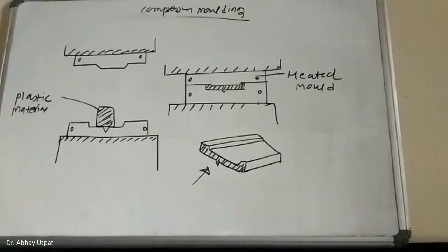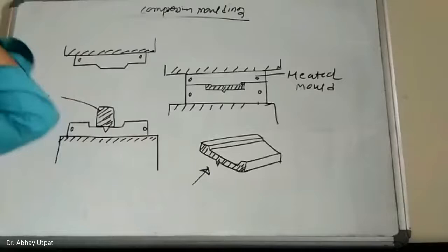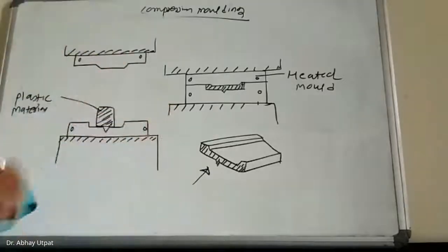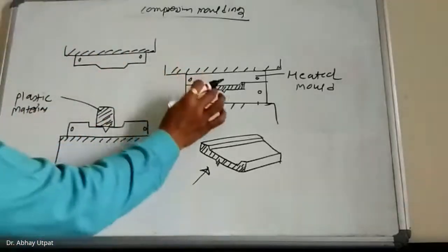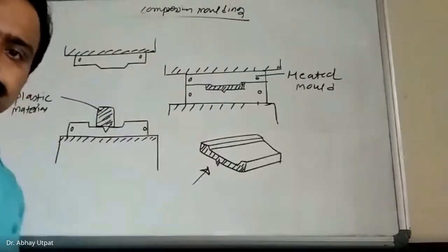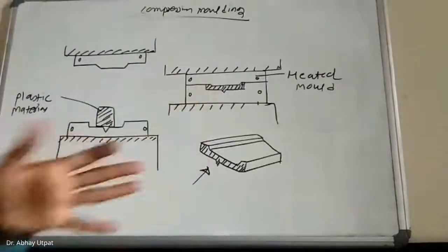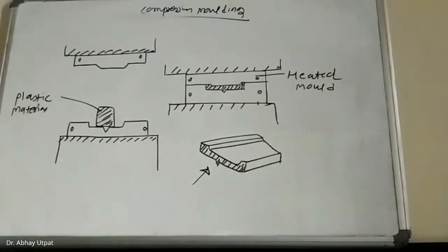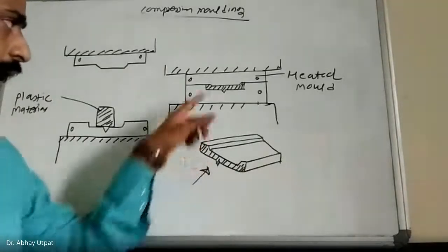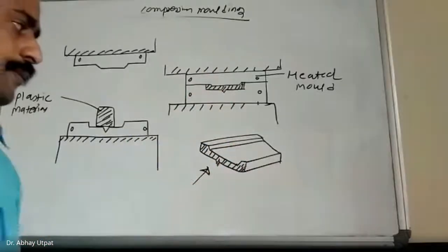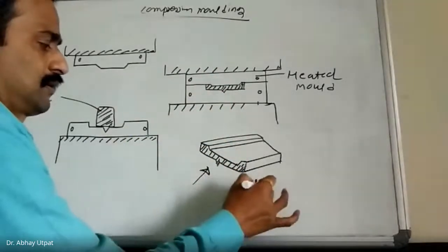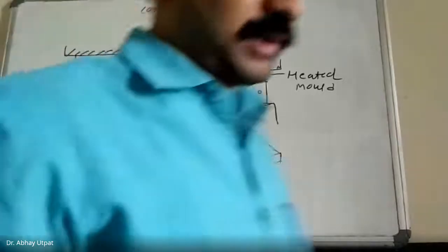Once you preheat the component, the plastic which is kept in the die reaches the plasticized zone, and once it reaches the plasticized zone, pressing will be carried out. After preheating, the next step is pressing. It is kept there for sufficient time till the material flows into the gap between the upper die and lower die, and then it is removed to get the product. Draw this figure.